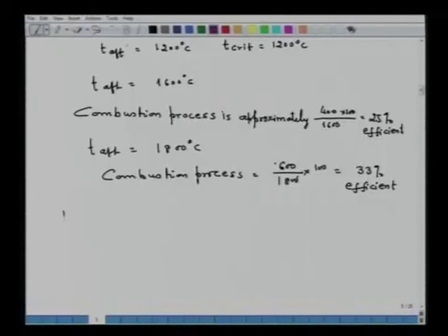For example, melting. If you just supply a gross available heat which is calculated on the basis of critical process temperature, then the metal may not melt, because you have not considered the losses which are occurring, because the amount of heat which is being lost through the wall or through the opening has to be compensated by extra amount of fuel. Therefore, another quantity is important, which is called net available heat.